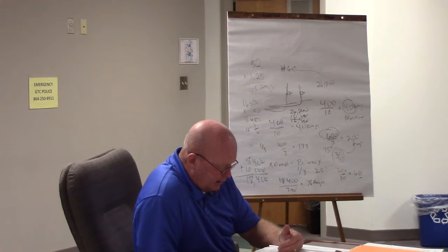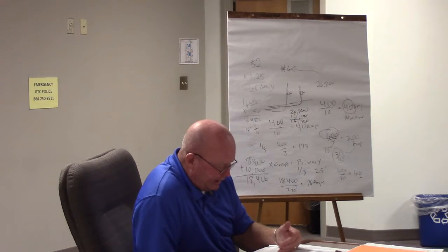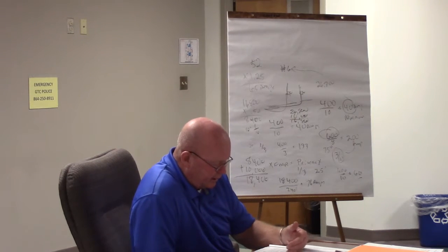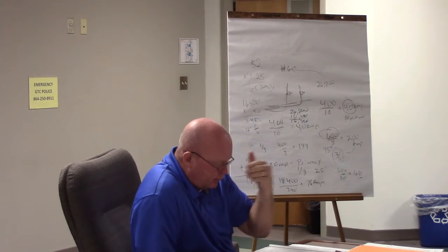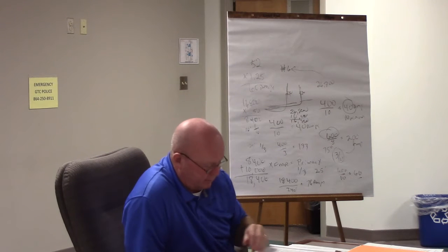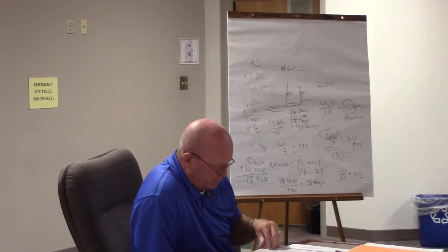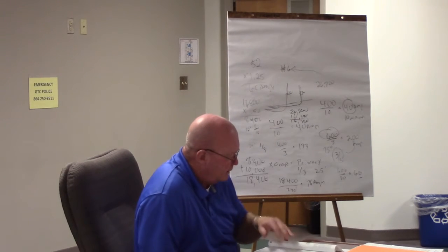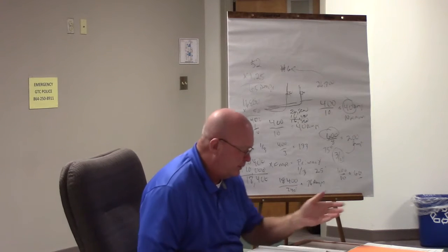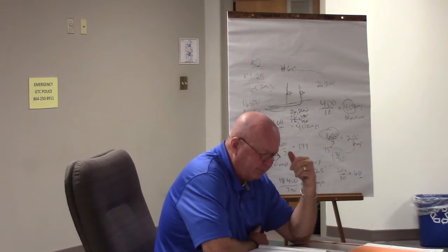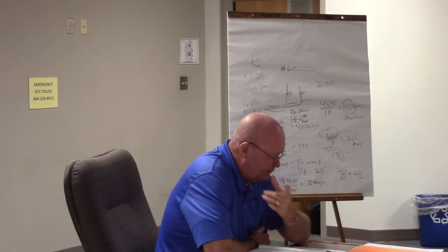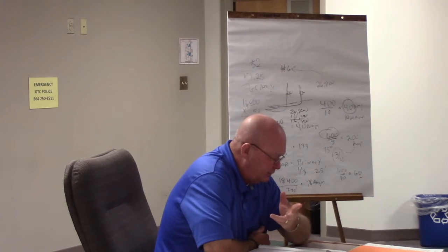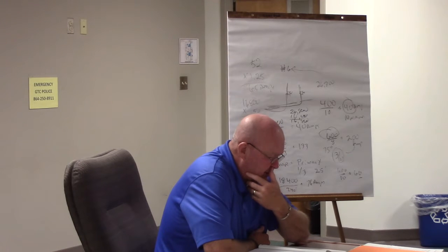Also, 310.15(B)(5) allows the exclusion of a neutral conductor carrying only unbalanced current when determining or adjusting the factor for 3 or more conductors in a conduit. A couple other things, and we'll wrap up and do these review questions. We'll call it a night. Service conductor considerations. Y'all can read that there. It's just got some definitions there that you need to see.